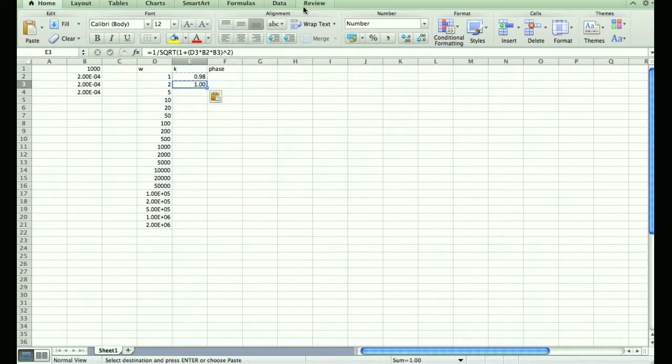The problem is it also advanced the cells where I was storing my resistor and capacitor value. Okay, so there's a little Excel trick. I don't know if anyone knows this. If I put a $ in front of the B1 and B2, it'll always use the same one. So now when I come down here, it incremented D3, so I'm using this frequency, but it's still using cell B1 and cell B2, which is where my resistor and capacitor values are. So it won't change those. So copy, paste. Okay, what do we got?